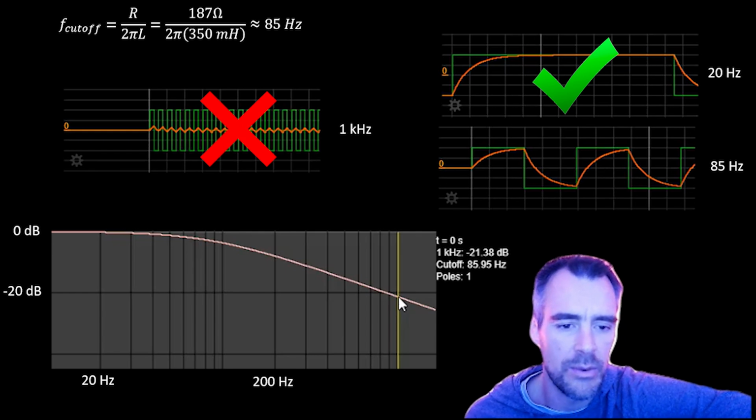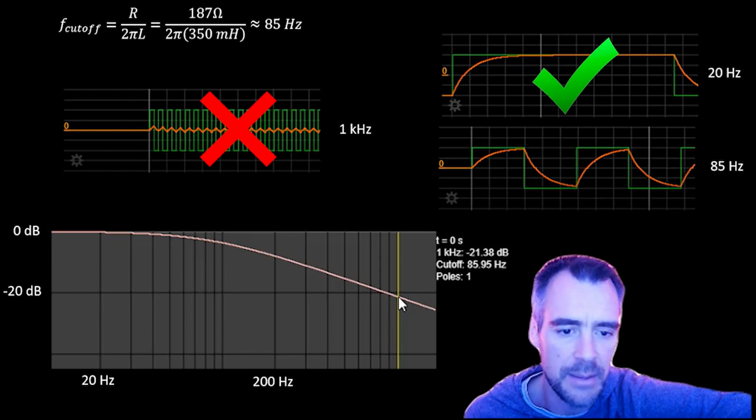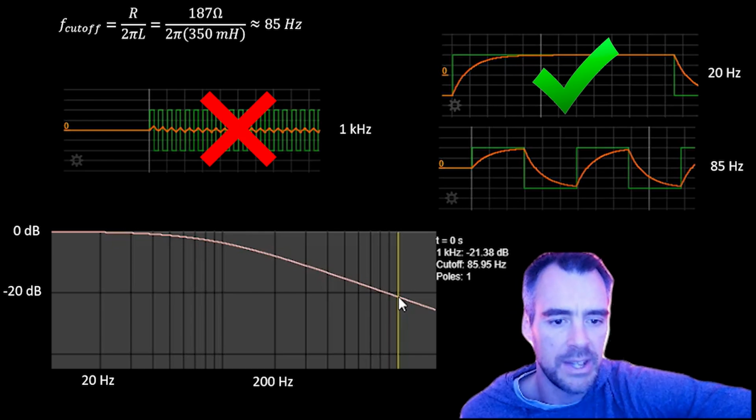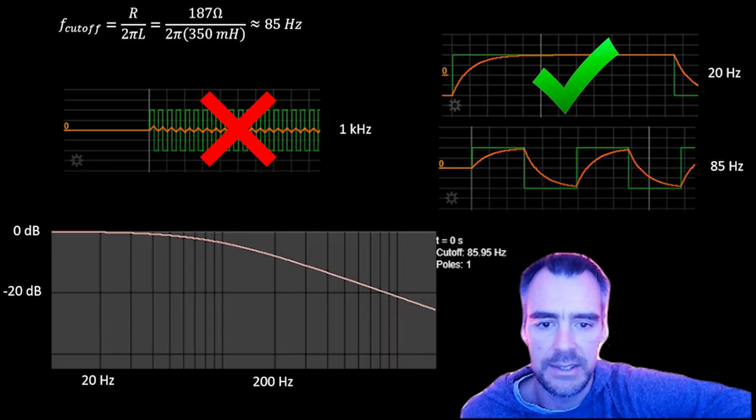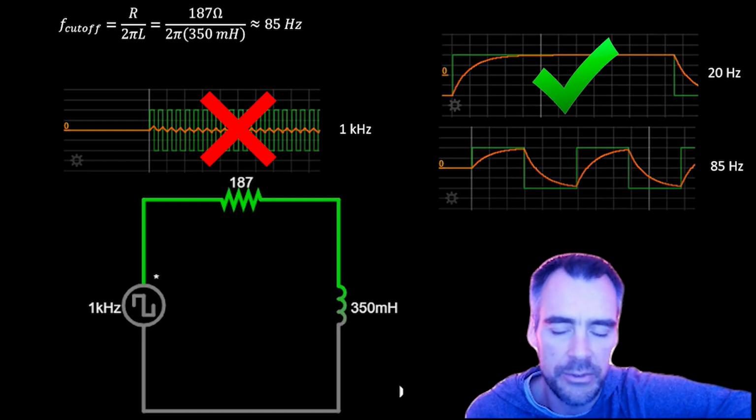And again, the rationale behind it is that the voltage across that resistor tends to want to follow what that source is, but it needs enough time to get there. So if you keep oscillating so fast, it doesn't have a chance to keep up, and so it won't track what that input signal is. But in general, I hope this explains how a low-pass RL filter works.